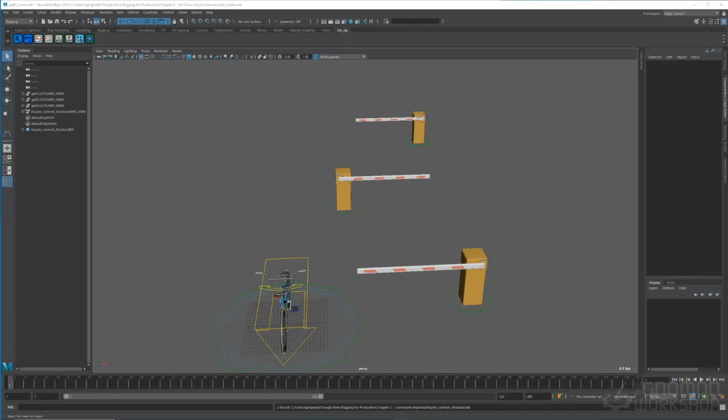It's never a great idea to import a rig, although that is what I did in this example scene. I did that because this gate arm is a very simple rig, and I wanted to make sure it exists in the scene when you open it. Because references are looking for a path on disk, I did not use them to build the scene.